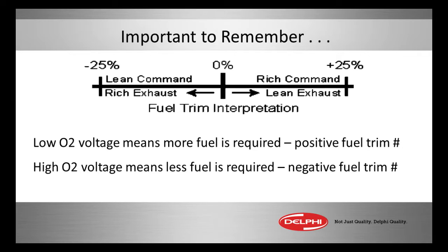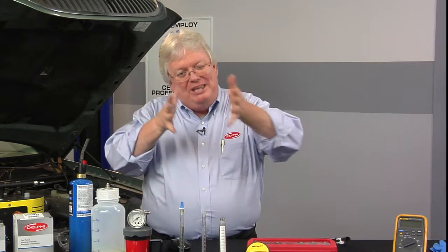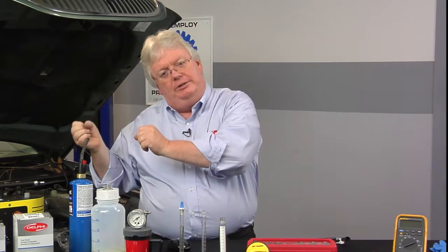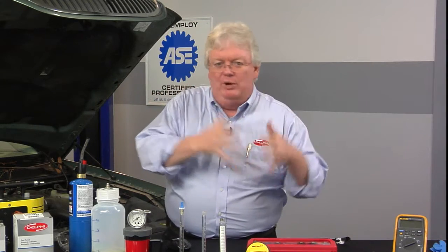And just to keep the relationship in mind, because a lot of techs don't pass ASE A8 engine performance, and especially those that don't pass L1 advanced engine performance for ASE testing, one of the big things they trip up on is the relationship between O2 voltage and fuel trim, and whether we're adding to the fuel injector base pulse width, a little more injector on time, or subtracting some base pulse width on time. What is base pulse width? You flip the key on and you see it.